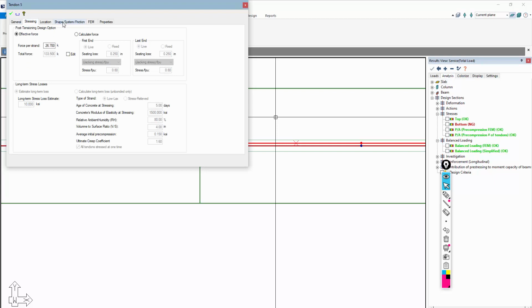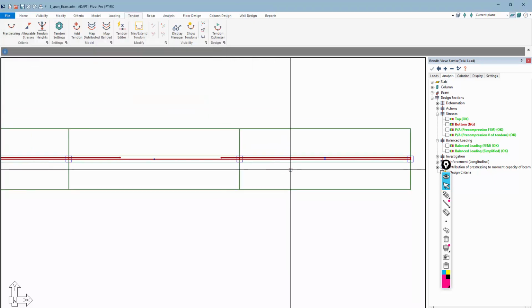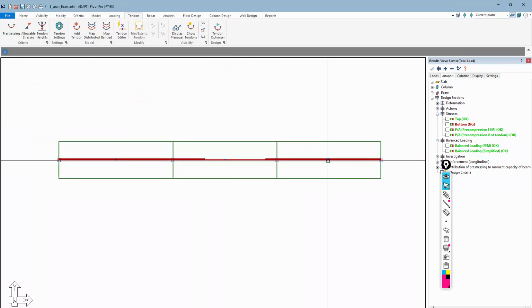We have our stressing setting, and then we can manipulate, let's say this tail, we'll say it's a cantilever down, and we're going to drop that down, let's say 3 inches, and raise that up 3 inches. Then over here we're saying that's 9 inches. So there's one add tendon. We have add tendon on this left side, right side,